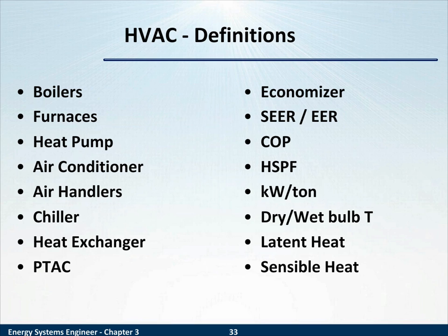Air conditioning, air handlers, chillers. You've seen a heat exchanger. Do you remember seeing that in the water side economizer? You've seen a PTAC, water and air side economizers. We haven't used the definitions of SEER and EER, but you have those definitions to maintain in context. They're a rating for efficiency. Likewise, COP and HSPF, kilowatts per ton, terms that illustrate the efficiency and effectiveness of a particular unit.